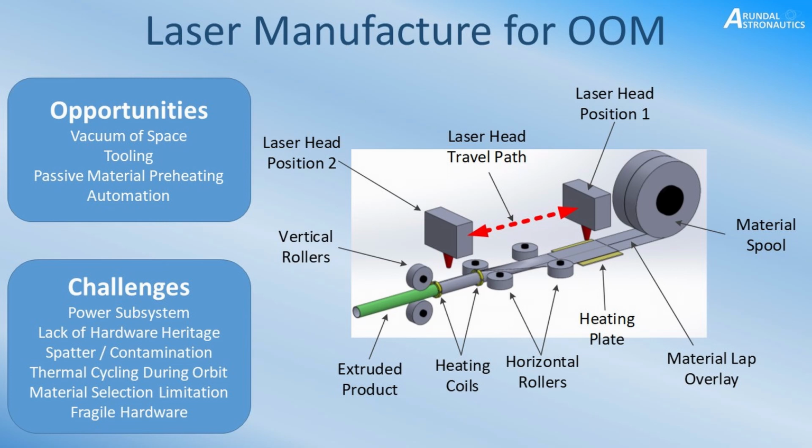Contamination is another challenge that we have to think about with laser processes, for example contamination on the laser lenses, or even the molten material from the laser process, or spatter, would certainly be an issue. If you can imagine random blobs of molten material being ejected from the workpiece in random directions due to the weightlessness of space, then you could perhaps imagine the problems that this would cause. Engineering analysis, therefore, would need to consider this and design accordingly to mitigate or even entirely prevent it.